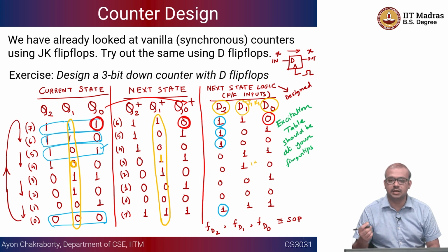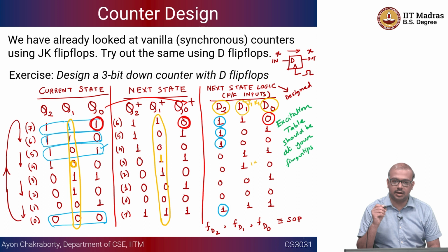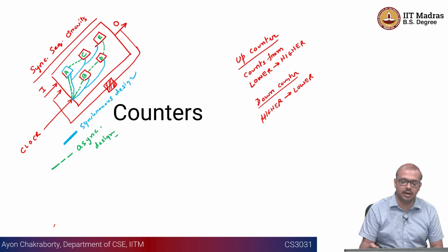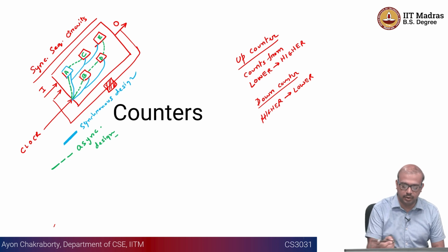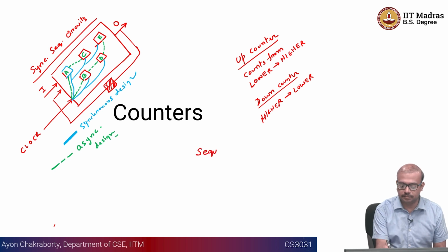And for that sequence, you see what are the different number of elements that are required in the sequence, and those have to be codified, that is the state encoding, right? I'll quickly discuss that one more time. Suppose I am trying to build something called a sequence generator.